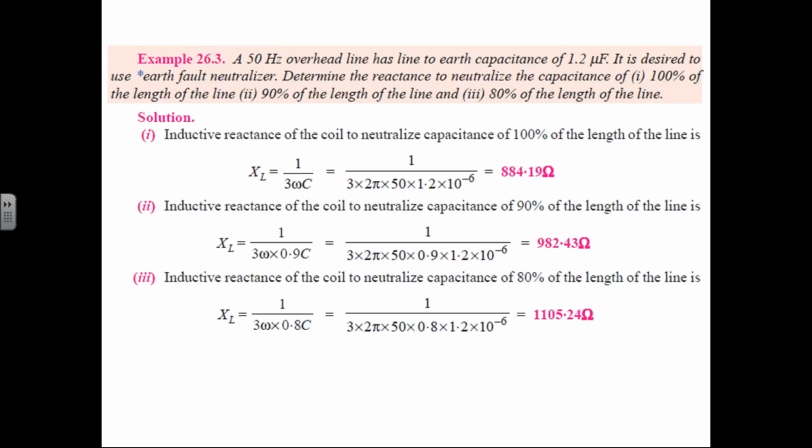So for this, determine the reactance to neutralize the capacitance of 100% length of the line, 90% length of the line, and 80% length of the line. This is nothing actually. We want to calculate the XL for three different cases: for 100% line, 90% line, and 80% line.